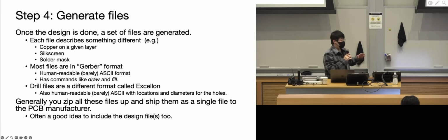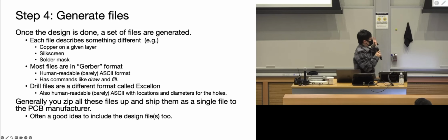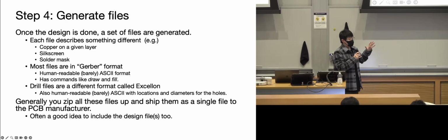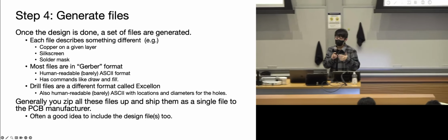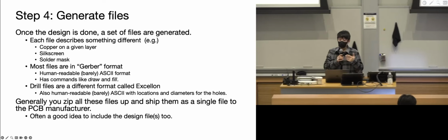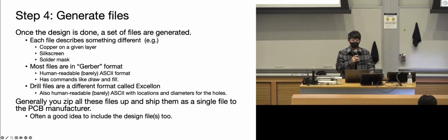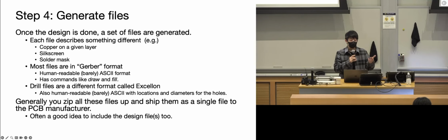And usually you just zip them up and send them to the PCB manufacturer. It's also good to consider including your design files with it, so that when their engineers inspect your Gerber files, if they run into some quick questions, they have something to refer to.